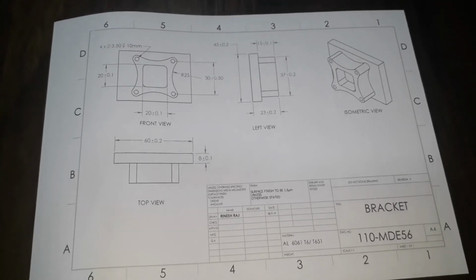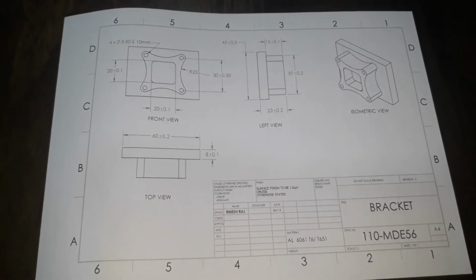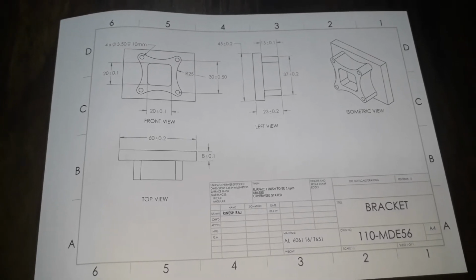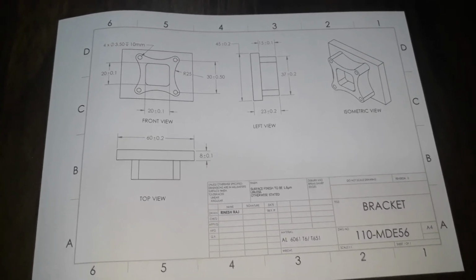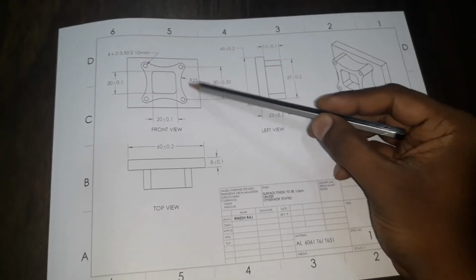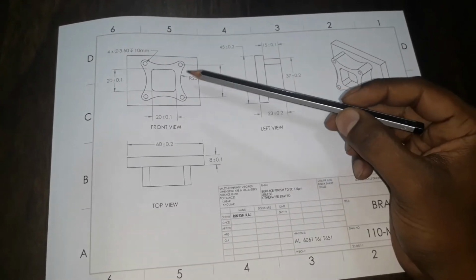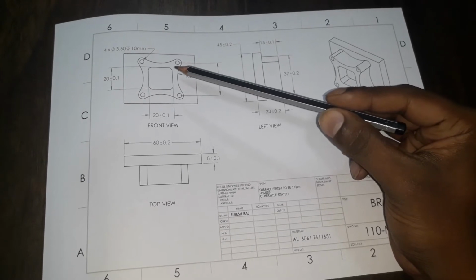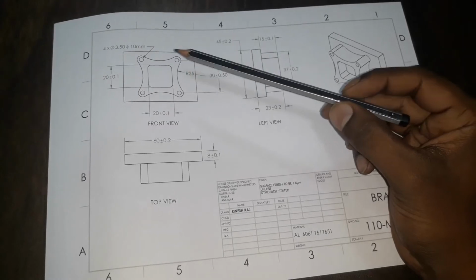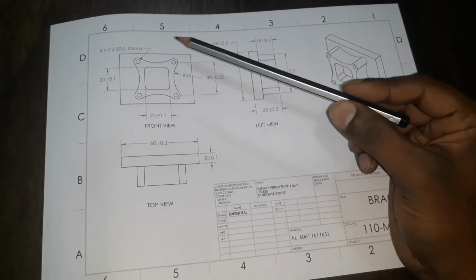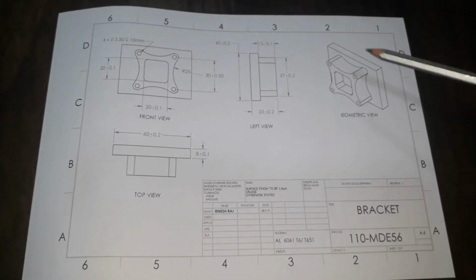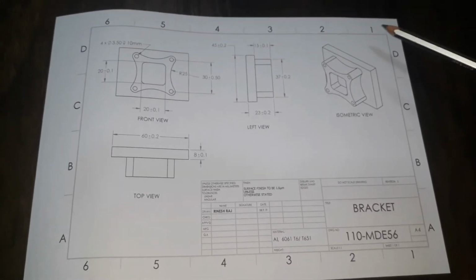How I would look into this engineering drawing is that I would first go ahead with a profile milling, so that I can get this particular shape out, and then I will machine this pocket, and lastly I would drill this 3.5 millimeter hole. So in short, then we can get this isometric view.